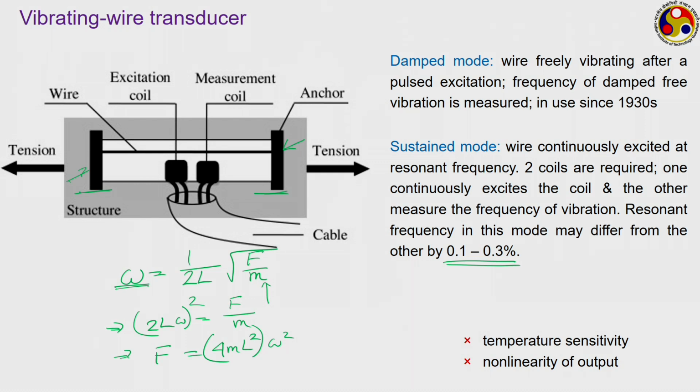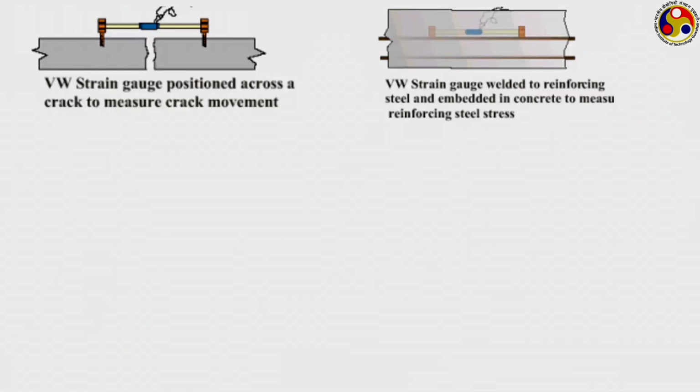while taking the output measurement. But these vibrating wire transducers are particularly suitable in permanent structures, like for measurement of deformation or crack generation in structures, like just shown here. Say we already have a crack, we know there is a crack somewhere in the structure and we want to see whether the crack is keeping on developing or just remains the same. Then we can